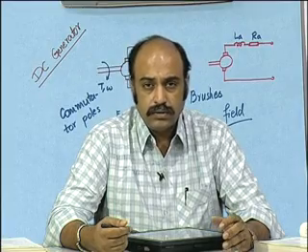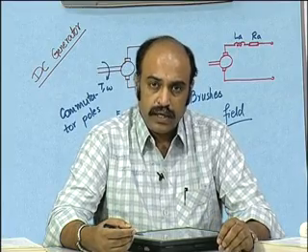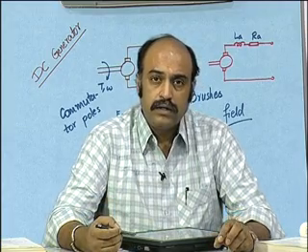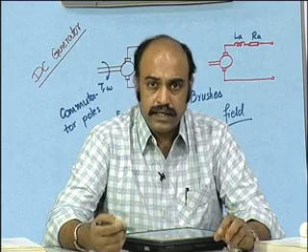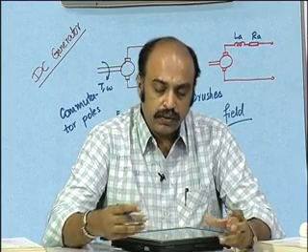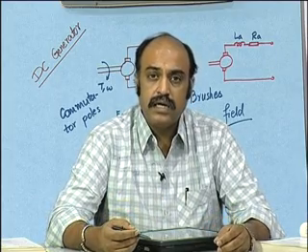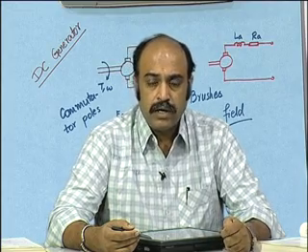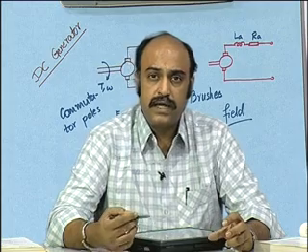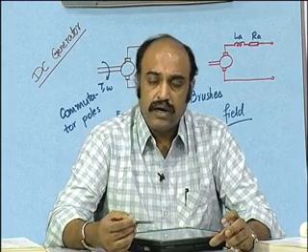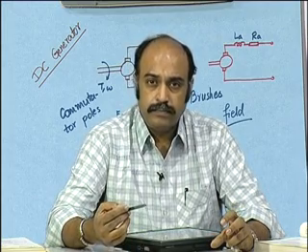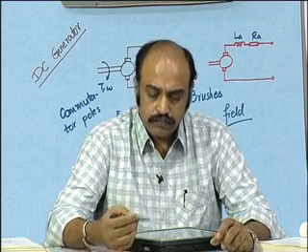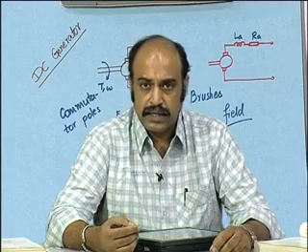The compound excitation consists of a shunt excitation plus a series excitation, which will try to compensate for the variations in the induced EMF. In the compound excitation itself, there are two varieties: the plain compound and the over compound, and then there is the differential compound, which we will discuss in the next class.